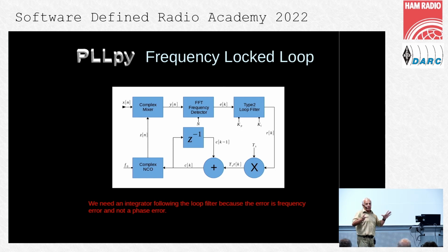Okay? In a project, we used it for the initial locking of the PLL because we have to lock for a very wide range of input signals. And we cannot do that with a normal PLL because due to the very bad SNR, we have to use a very small bandwidth before the phase detector.